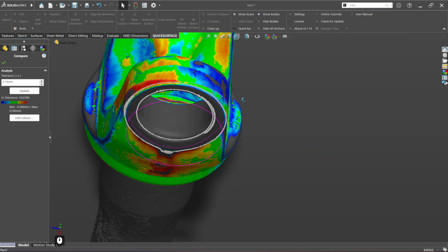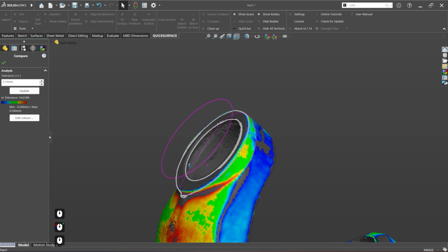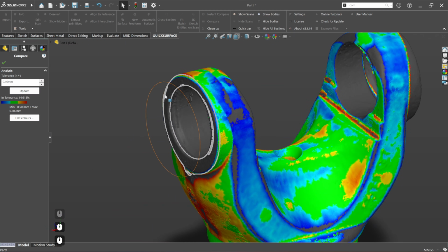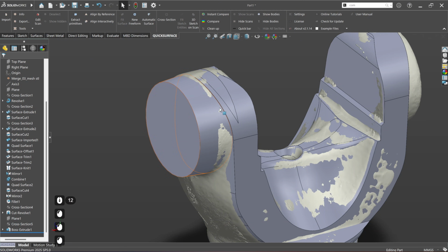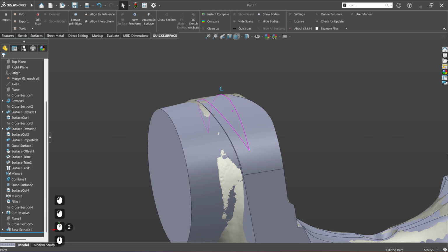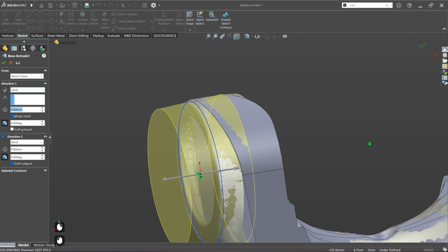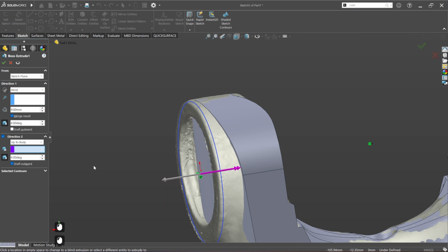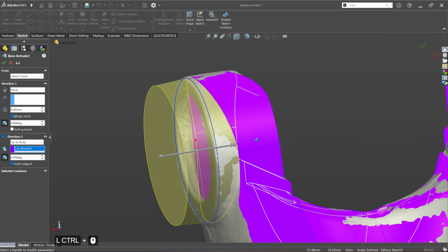So in this case, we have to figure out some solution how to solve this, and let's get rid of our cross sections, and actually let's come over to edit our extrusion and set direction to up to this body, like this.